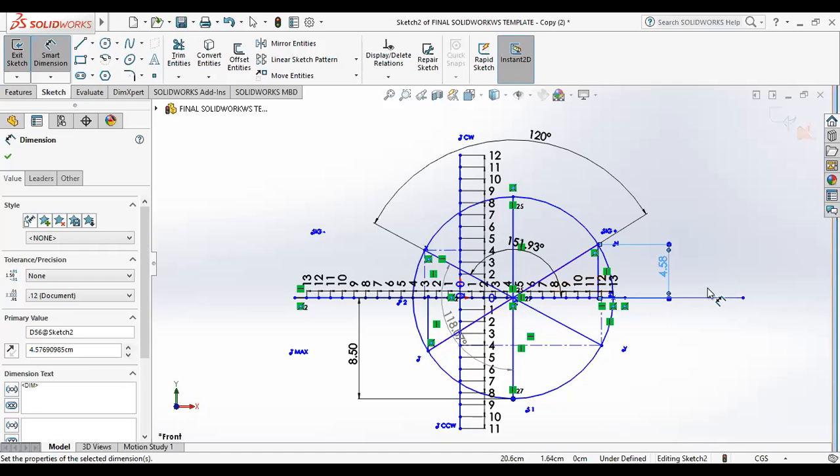Since this is the sigma axis, whatever you measure here, always measure with reference to the origin, not from the center. From the origin, whatever you measure to this point, say around 118 point something, is your sigma x dash. This is your tau dash, 45.8. Similarly, whatever you measure from the origin to this point is your sigma y dash. This is 28 point something, and this height remains the same, tau dash 45.8.